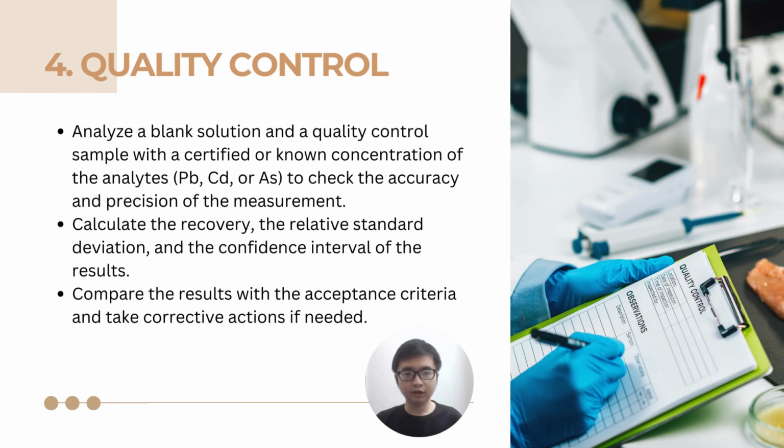Next is quality control. The quality control measures can be run by analyzing a blank solution and a quality control sample with a known concentration of the analytes, lead, cadmium, and arsenic. Besides that, the recovery, relative standard deviation, and the confidence interval of a result should be calculated and compared with the acceptance criteria to ensure the reliability and accuracy of a result.